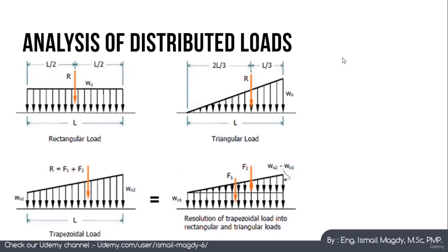It is to be noted that we cannot deal directly with distributed loads, and that's why, in order to analyze any distributed load, we need to calculate two main things, which are the resultant force and the location of the effect of this resultant force. The value of the resultant load is simply calculated as the area of this load, while the point of the effect is the centroid of this shape.